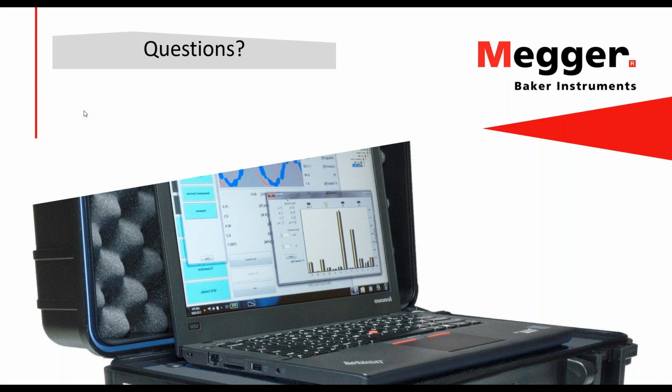So I would say that they can both complement themselves, because you can also find problems with this that you cannot find with vibration monitoring. So I would say that this tool and the tools associated with vibration monitoring intersect, but they cannot replace each other. This is a complement to vibration monitoring that expands the amount of information that you can get out of the motor, and the amount of predictions that you can make on the life of the motor, and it improves the maintenance program that you can do on those rotating machines.